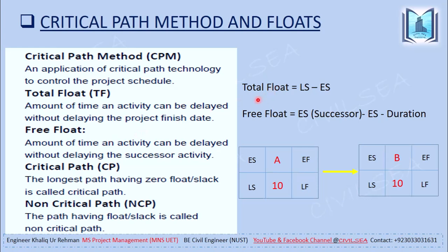Here you can see that total float is equal to late start minus early start. Free float is equal to the early start of the successor activity minus the early start of the activity minus duration. Moving forward,